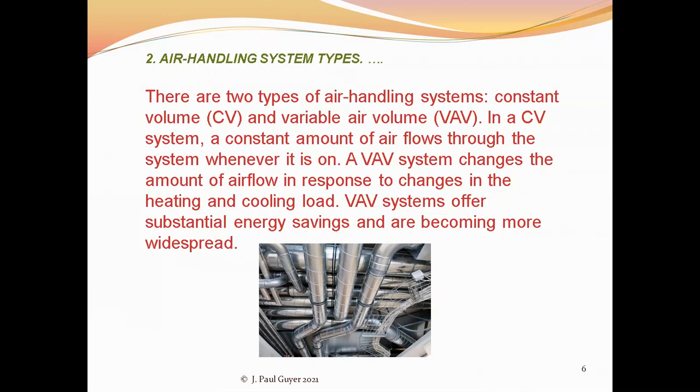And the air in a VAV system is at a constant temperature, and it is the volume that is adjusted. And that's the state of the art, if you will, with air distribution systems. The VAV systems offer substantial energy savings because, first of all, you're not changing the temperature at which the air is delivered to the occupied space.